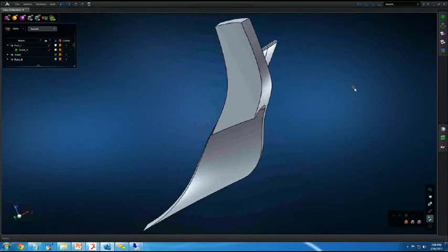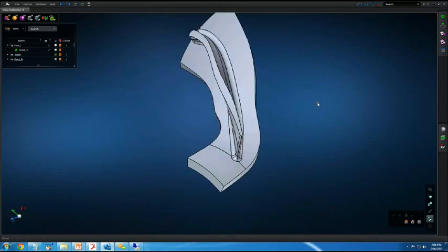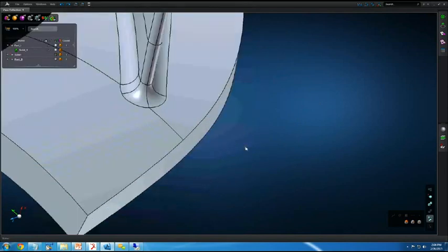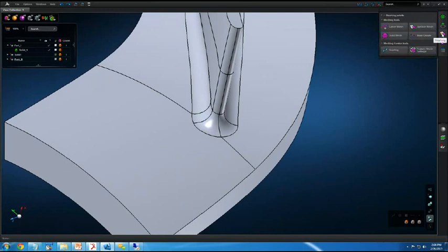So now I'd like to show how we can mesh in Apex and then export that mesh into Patran and use it as a seed to mesh this entire solid body. Okay, and just for a simple example, we're going to mesh just a few of the faces on this leading edge here. So I'm going to go to Meshing, Surface Mesh.